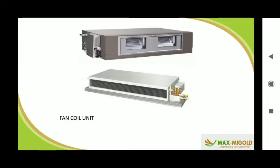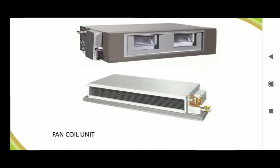Then this is also another ductable unit. This one at the top is a ductable unit, but this other one is a fan coil unit. They work exactly like your split unit. The only difference is that their design accommodates them to be inside the ceiling. You only duct it out and use a diffuser to distribute the air within the required space.